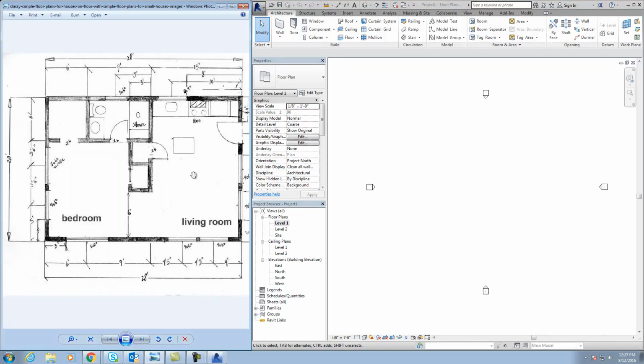All right, we're going to get started. First thing I want to do is build a wall out here. Now this one, I don't have anything specified. Let's say it's a 2x4 wall, and we have a 1/2 inch sheetrock on the inside. Let's say we've got a 3/4 inch outside board here, and the corners will be plywood, and in between could be insulation, and then on the outside we could do siding or something to that effect. And I'll show you how to do that.